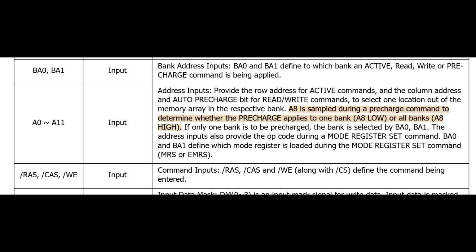I also found datasheets from various memory modules that have 9 address bits, and they kept the address bit on A8. Despite that being part of the column address, that's not a limitation. They kept on using A8 as the auto precharge pin. So now I needed to work around this issue. And it is very fortunate that at this point I stumbled across the Xbox source code leak.